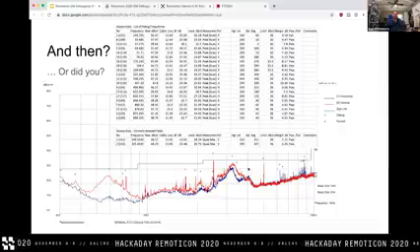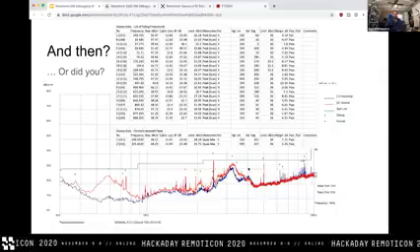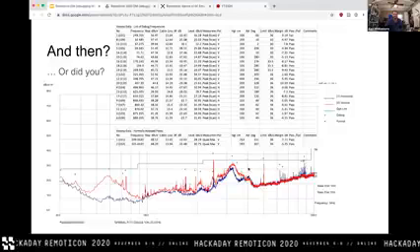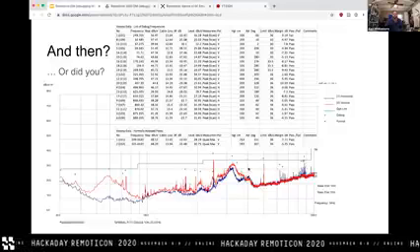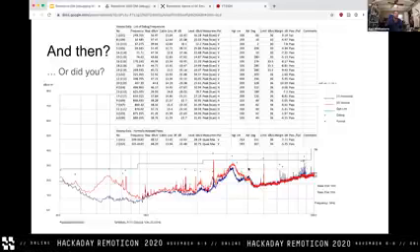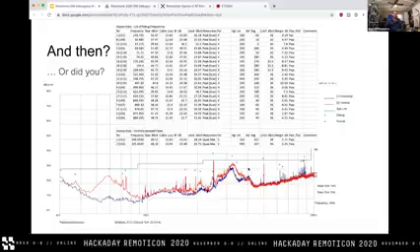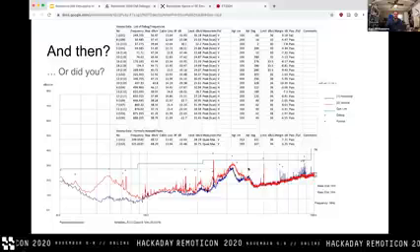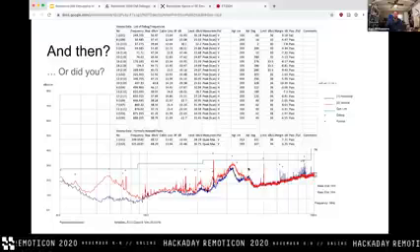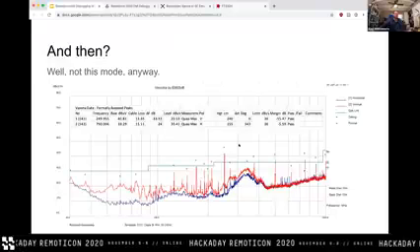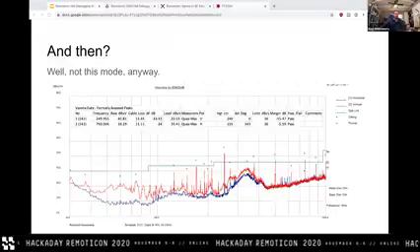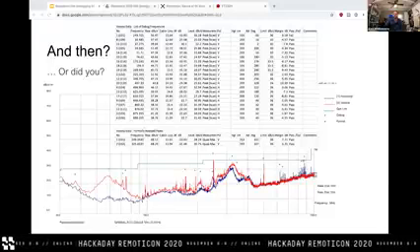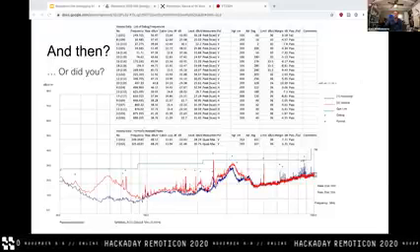And then because it's Ethernet, it also involves a wireless backhaul. So you can choose wired Ethernet or wireless, which means there are 4 total test conditions. And it turns out that this device performed just fine under wireless conditions because there may or may not have even been an Ethernet cord plugged in. And as I'll describe later, or right now, I guess, this device basically only fails its emissions testing under connected to Ethernet conditions.